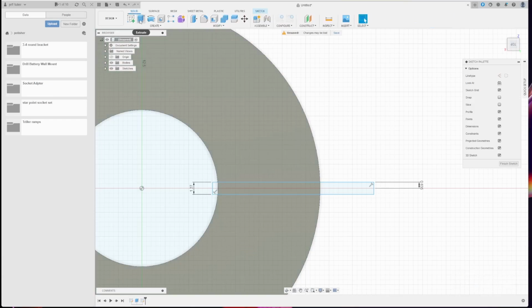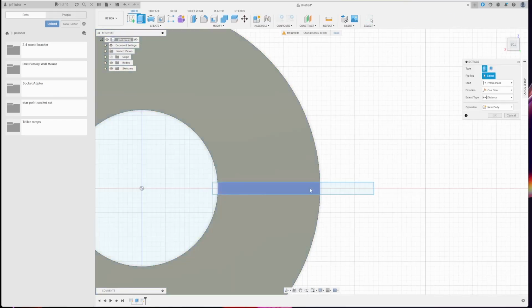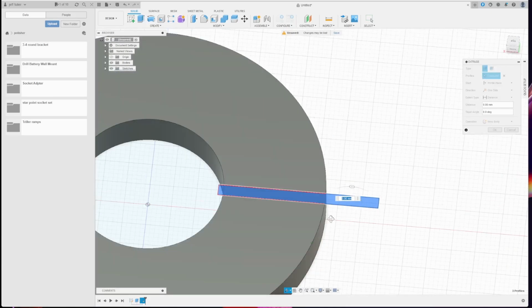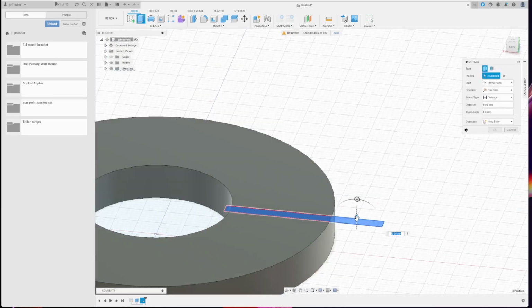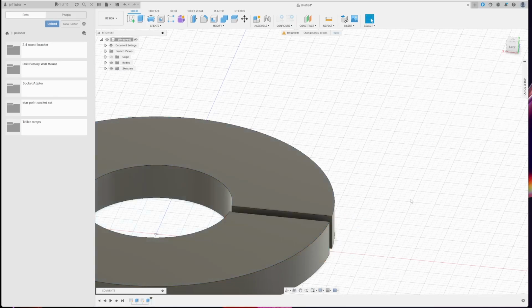Going back to solid and extrude, I can select that box, and I'm actually going to select all 3 elements because our solid model is going to make a separate element. And then I'm going to use shift to rotate down and look, and it wants to extrude from that top face. I want to cut, so I'll just take my arrow and pull it down, and I don't have to be super particular or careful here as far as size. I can just pull it all the way down through the point, and I can press OK.